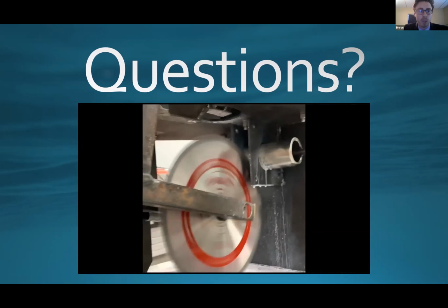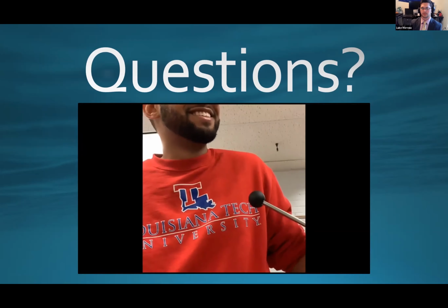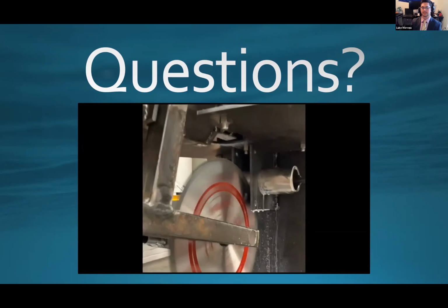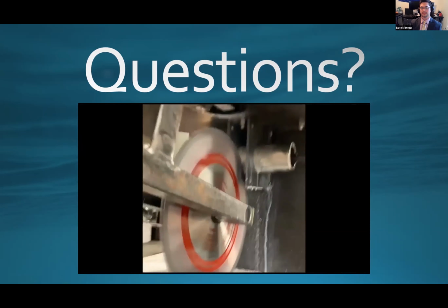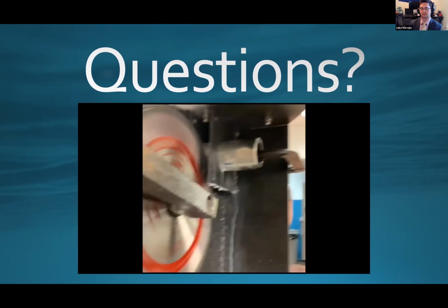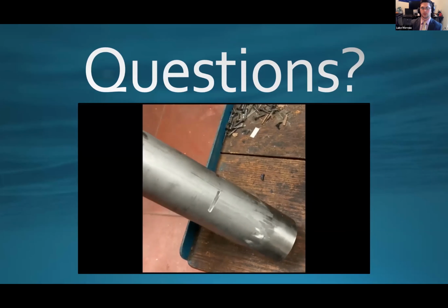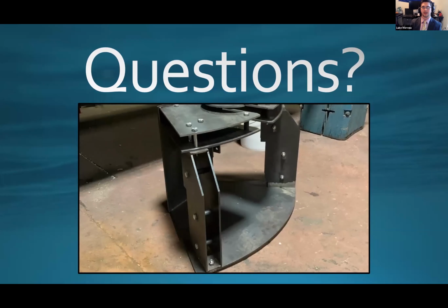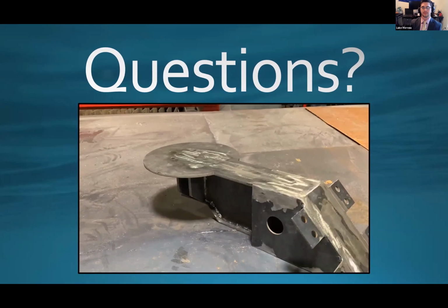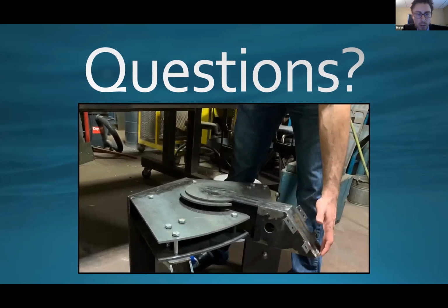But Luke, do you have anything you want to add? Yeah, I think I understand your question. Part of the way they're going to make sure this tool is properly in place and the lead screw is cut all the way through is that there are, I believe, 7 cameras on the ROV, so they will be able to see it. But we also designed a whole bunch of wedges into this thing, and the tolerances, to make sure that if there was anything in the way, the tool would work its way into the keyway. That's a good picture right there.